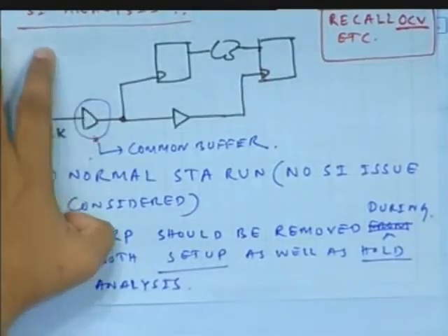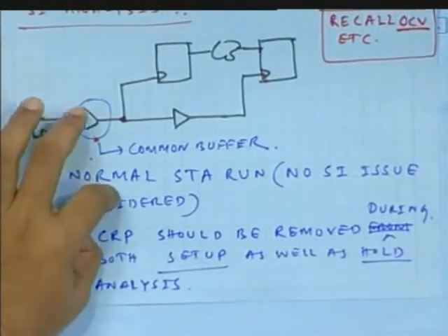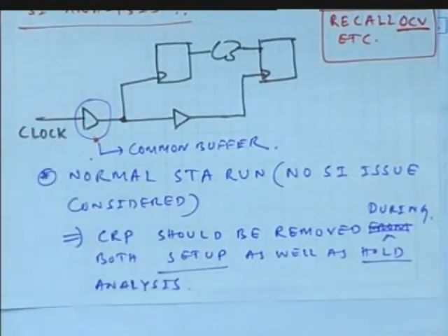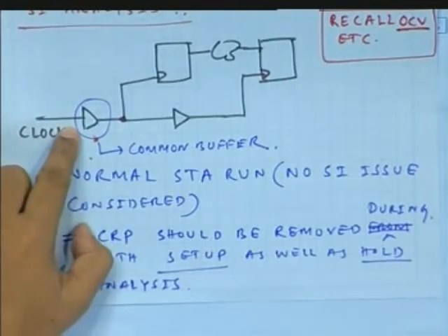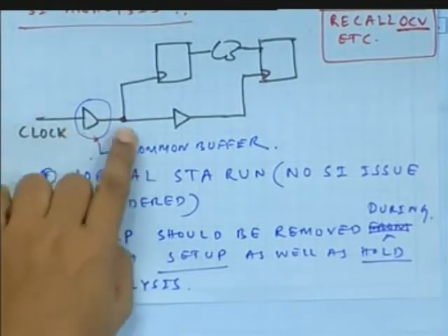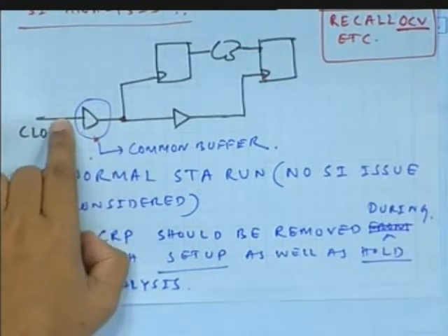See, I have just shown these nets. Assume there are so many nets running parallelly. So even at that point, the crosstalk happens before this buffer, before reaching the point at which you are saying. This point or this point? This point.